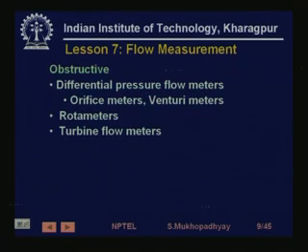Flow is one of the most widely measured and controlled variables, especially in process industries, because for temperature control you have to do flow control, for example steam flow control. For level control you obviously have to do flow control, because level is nothing but flow integrated.